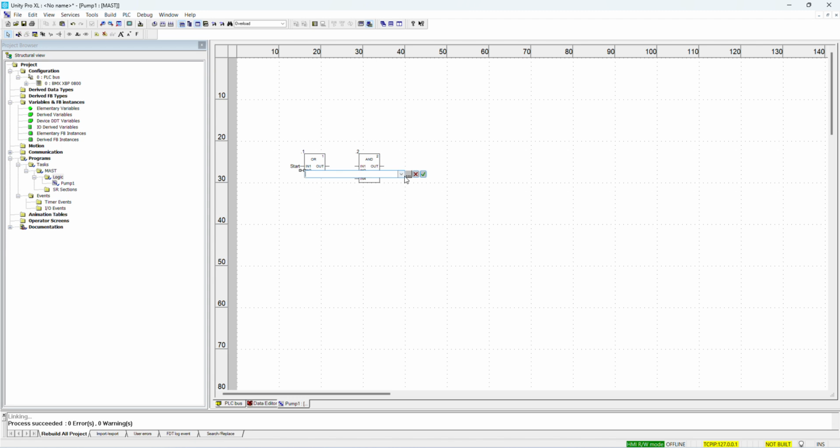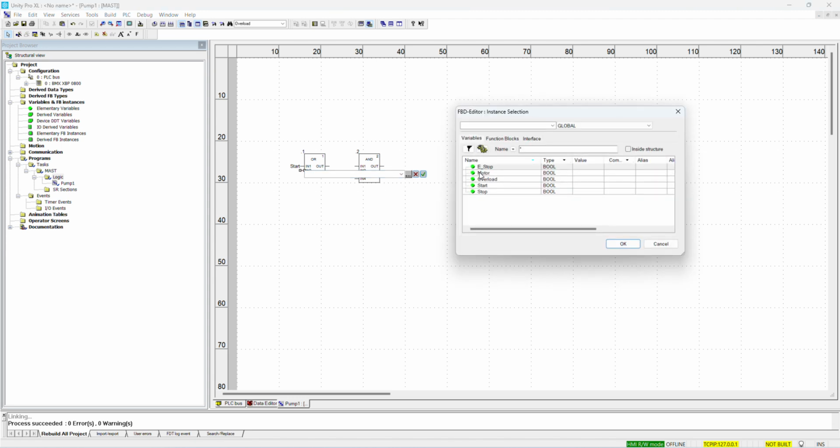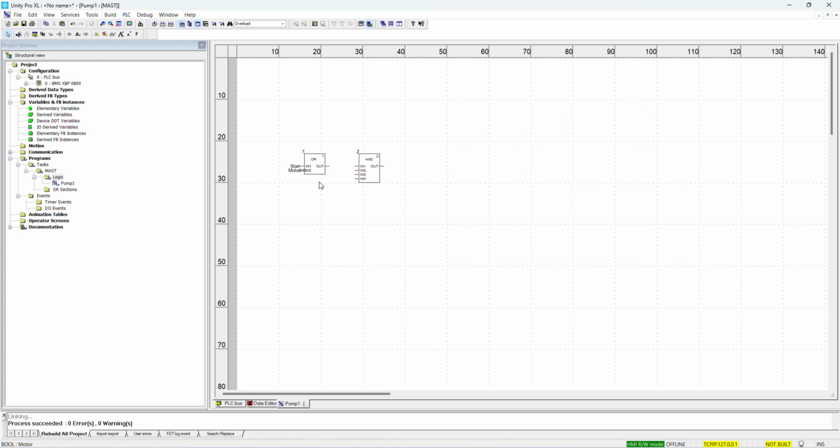Then I'm gonna double click there and then insert start, and I said or latch, which would be the normally open of the motor. And then this one I'll click here. Sorry, I'll click here. Okay, it doesn't want, we can go there and look for a link. And then we come back, click on that and link it with that. And then right click to remove that.